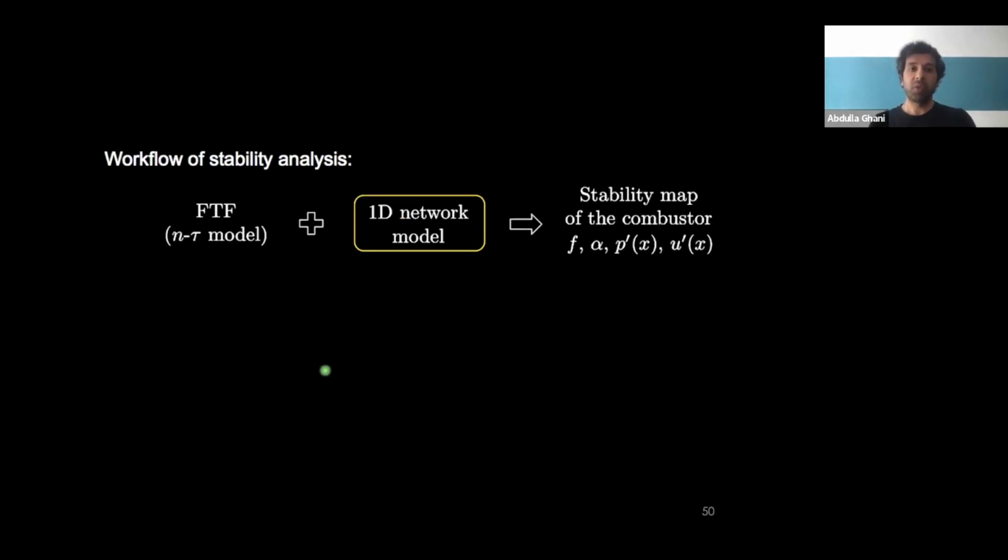If you recall the workflow that I showed before, one super important element is the flame transfer function, and the next important element is an acoustic solver. Before I showed a Helmholtz solver, which is a 3D solver, and now I'm talking about a 1D solver, which is basically the same if you consider one-dimensional acoustics.